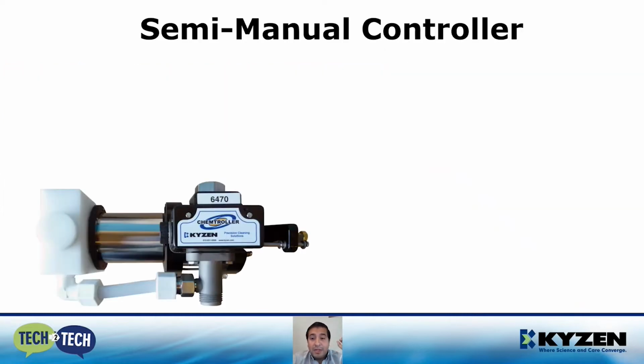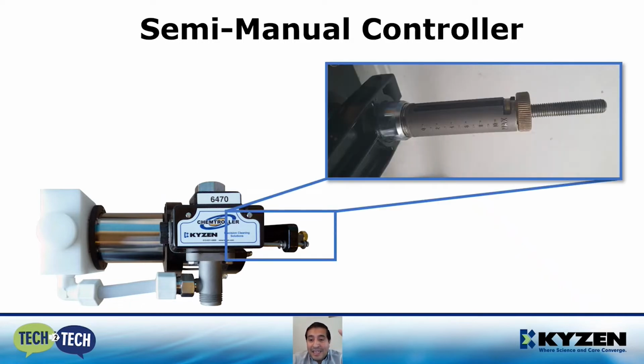The controller contains an adjustment dial that restricts the movement of the piston that is injecting the chemical. This dial allows us to set the desired percentage of chemistry to be injected into our process to refill the loss in levels in our wash tank. This adjustment needs to be fine-tuned to adequately maintain the concentration between your recommended process range.